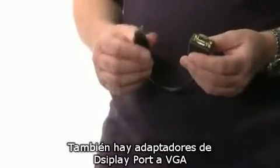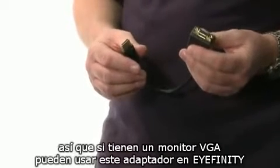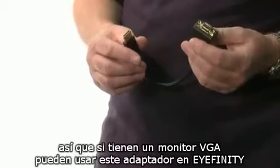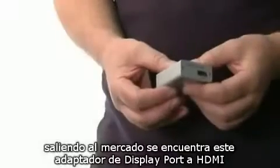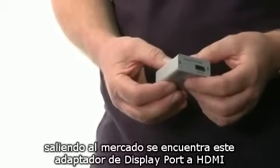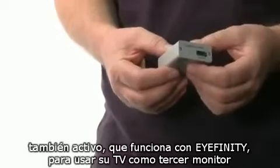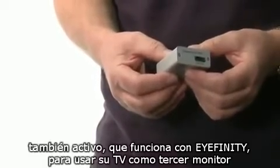There are also active DisplayPort to VGA adapters, so if you have the earlier type of monitor, then you could use this type of adapter to work with Eyefinity. Just coming onto the market now, there are also some DisplayPort to HDMI adapters, again active, so they work with Eyefinity, which could mean that you could use your TV as the third display in an Eyefinity setup.